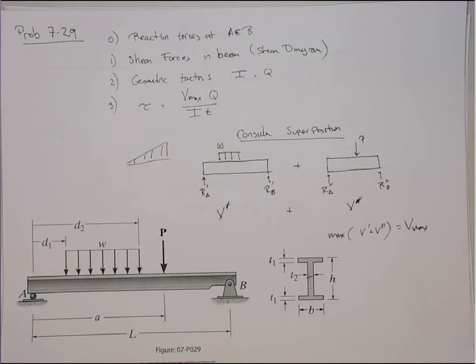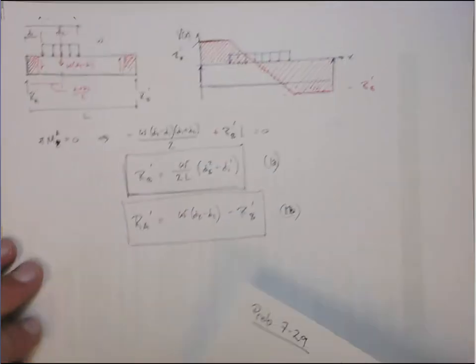If there's an error in the way I derive the equations, and I use the same equations to compute the transverse shear with the numbers, it'll have those errors in it. Whereas if I do it with a different approach, like our general approach, an error in the equations or the implementation of the equations will be picked up. So it's a good trick for debugging, all right?